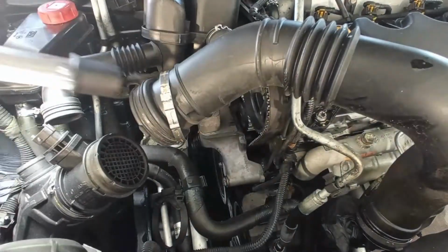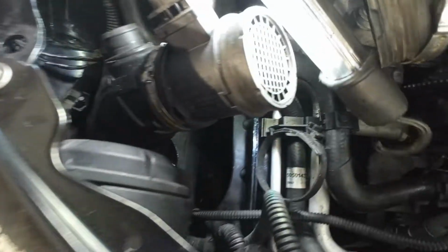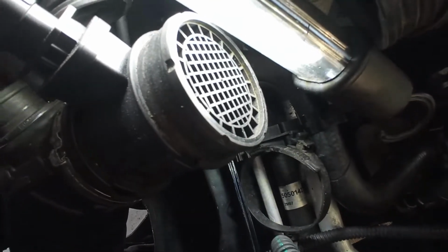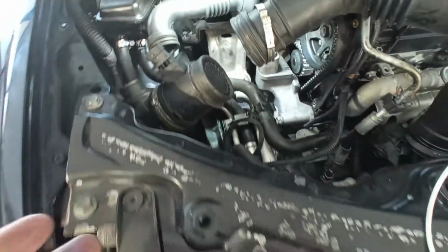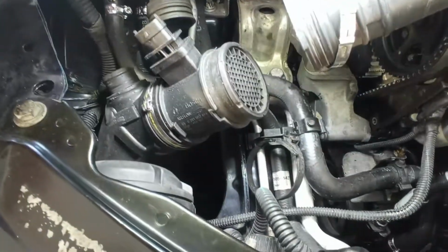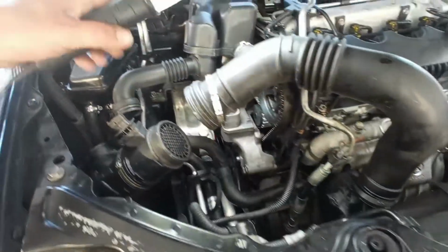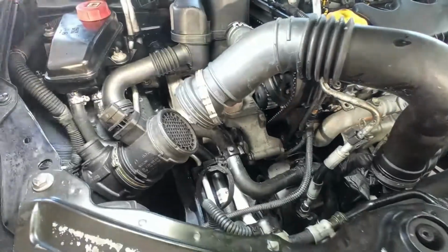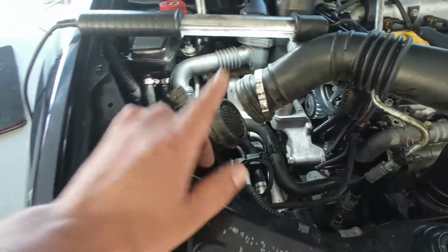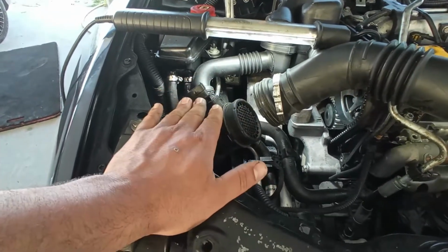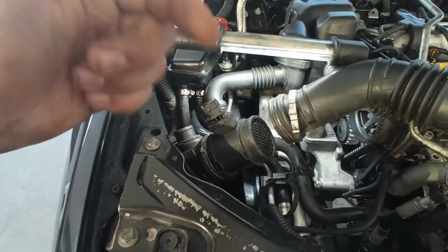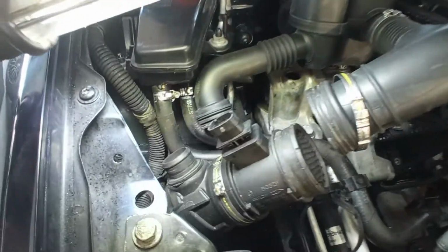Taking this apart, I noticed here on the inside of the mass airflow meter a lot of dirt. That cannot be good at all, which means that at some point this intake had some problems, some leaks, possibly some accident, and some dirt was aspirated through the engine. This is no good for the engine because the inside of the pipe is completely filthy, no good for the mass airflow meter. But right now, the diagnosis that I did indicates that it is functioning correctly. For that procedure, I do have a video. It is down on the description so you can see how it is done, okay?